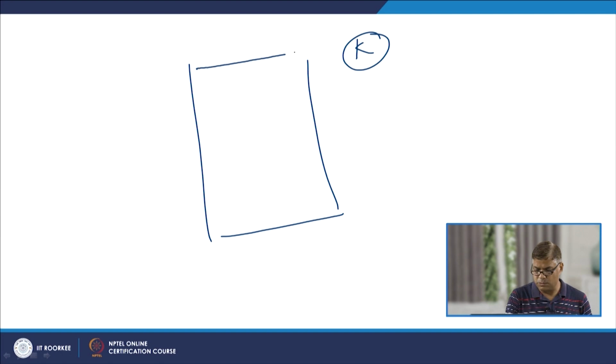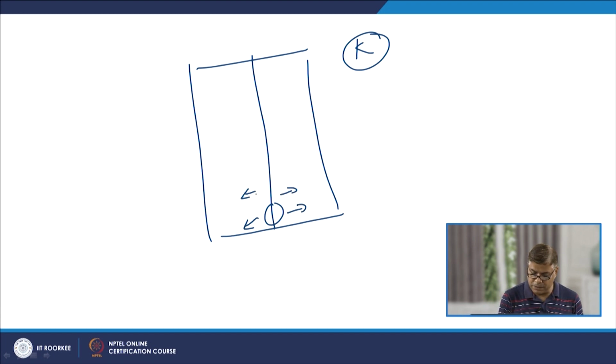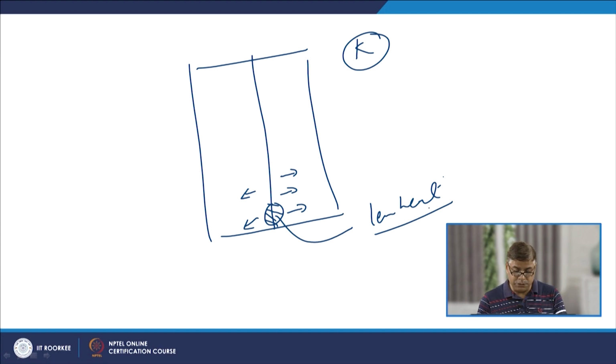Likewise, the thermal conductivity K of the stainless steels is very low. So, during the welding, when the heat is supplied for melting the faying surfaces of the steel, due to the low thermal conductivity, very little heat is dissipated to the underlying base metal, and most of the heat is utilized for fusion of the faying surfaces. That is why less heat needs to be supplied for welding of the stainless steels as compared to the carbon steels.